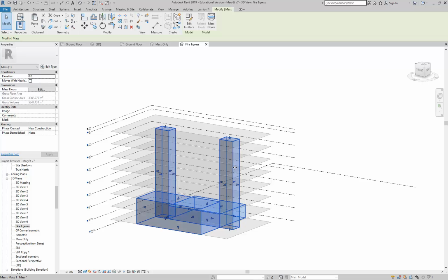Enclosed, yeah, absolutely. Distance between them. Certain distance apart, yep, so we've got both of those things. They're enclosed and they're separated enough. The distances to the points on each level are okay. So then, what we say, the distance to the exit, well, these are the exits, but to open space, yeah. So we've got to have a connection to open space, a horizontal exit, in other words.